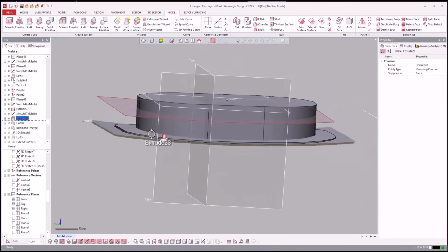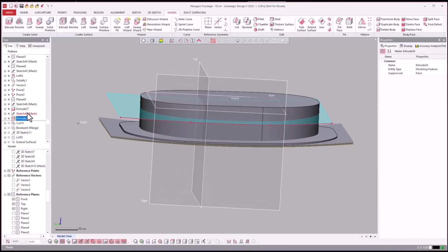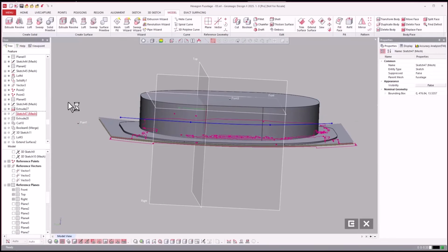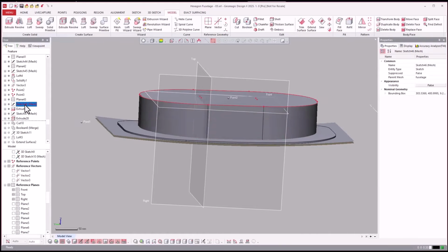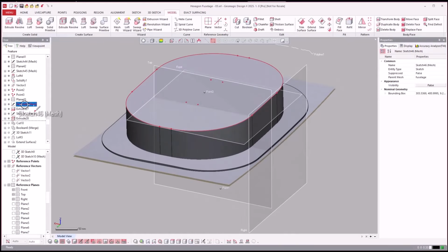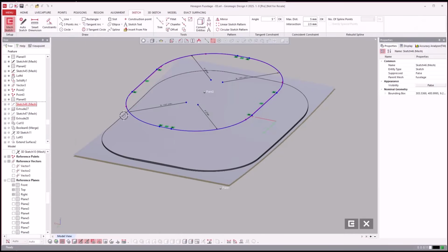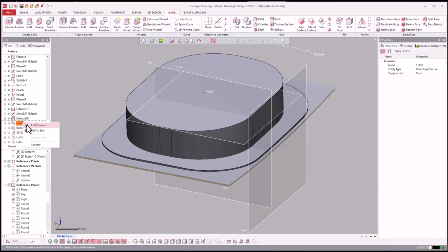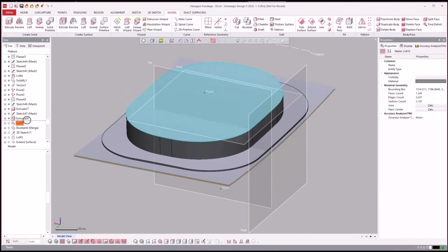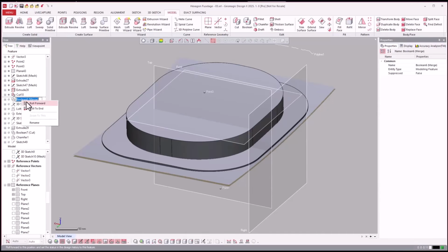So now on this piece, we went ahead and created this, and all that is a silhouette. If you edit that, you see here, we just silhouetted the hole in the middle and extruded that shape. Then from the side we did a silhouette surface there, cut that top surface, and Boolean these together.